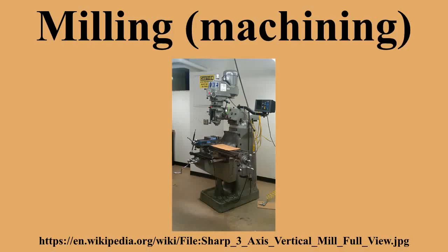The speeds and feeds used are varied to suit a combination of variables. The speed at which the piece advances through the cutter is called feed rate, or just feed. It is most often measured in length of material per full revolution of the cutter. There are two major classes of milling process. In face milling, the cutting action occurs primarily at the end corners of the milling cutter. Face milling is used to cut flat surfaces into the workpiece, or to cut flat-bottomed cavities.